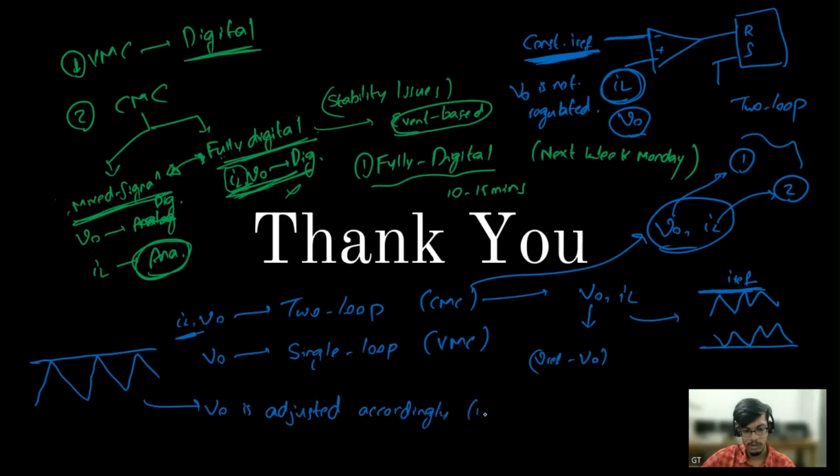Yes, sir, that is clear. If I use only single loop control for VMC, then won't the current be controlled? No. In single loop control, we are regulating V0, but we don't have any control over inductor current profile.